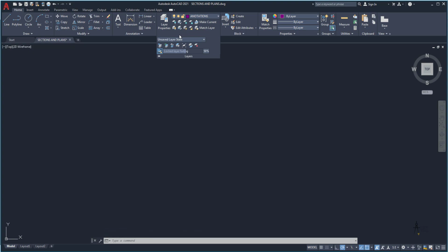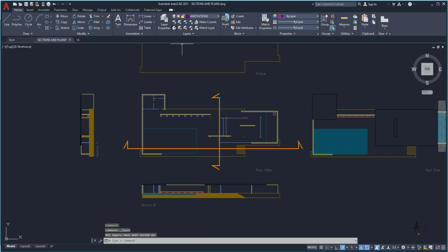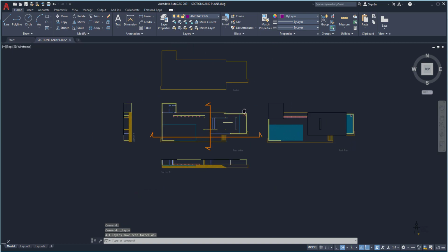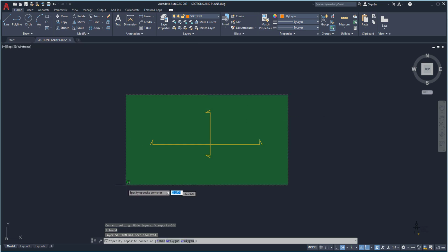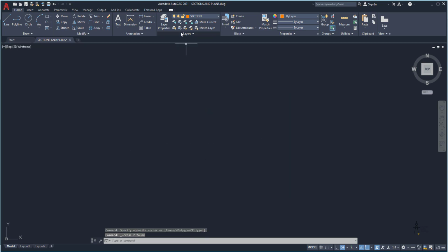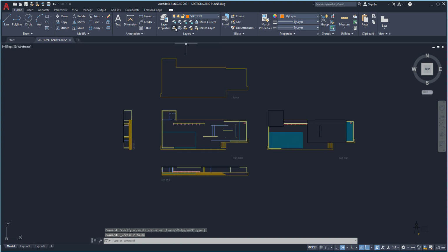You can't just hide your layer, okay? If you hide the layer, SketchUp will identify the lines in the layer, so you actually have to erase the lines that you don't want, okay? Then you've got these lines that tell us where the section is. Again, erase.